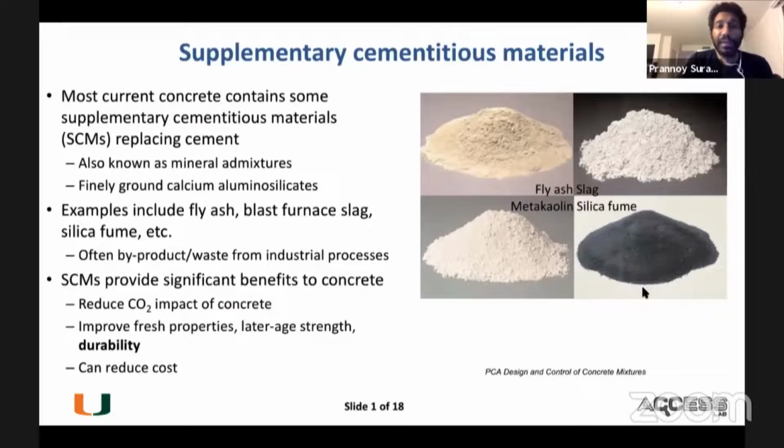So the reason for using supplementary cementitious materials is that they provide very significant benefits to concrete. And these benefits range from reductions in CO2 impacts. And that's a big thing because cement has a very high CO2 impact, and using these SCMs reduces that CO2 impact. SCMs also improve fresh properties and later age strength, but most importantly, they improve concrete durability, which is a major reason for the use. They also reduce cost in some cases.